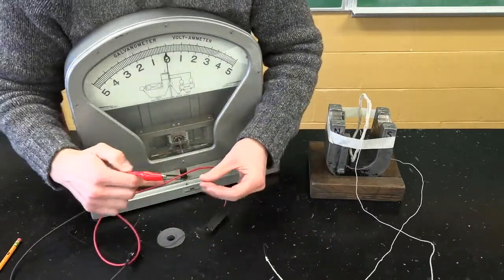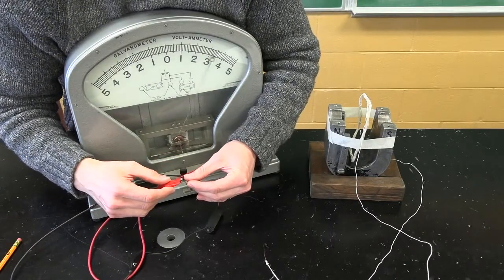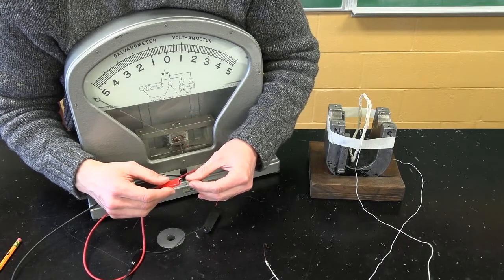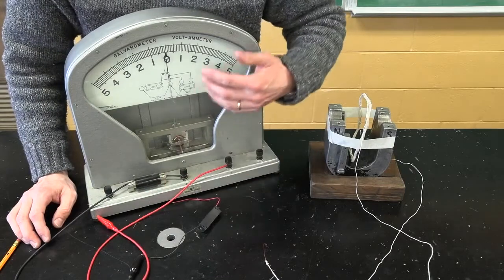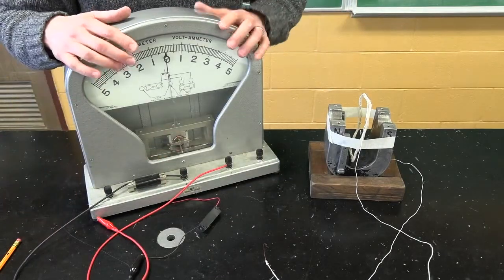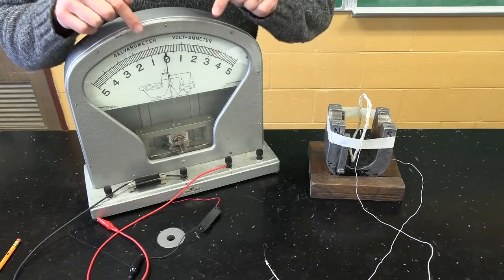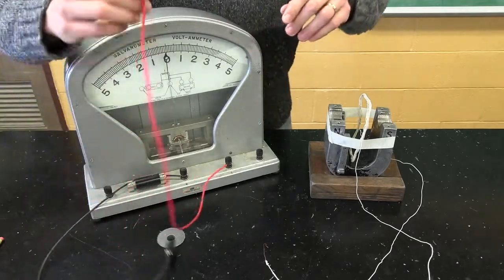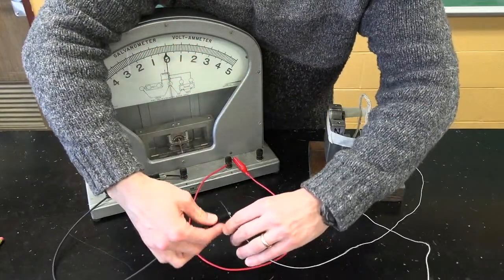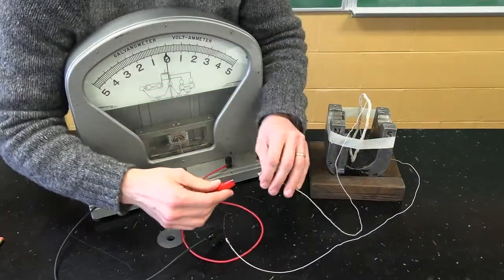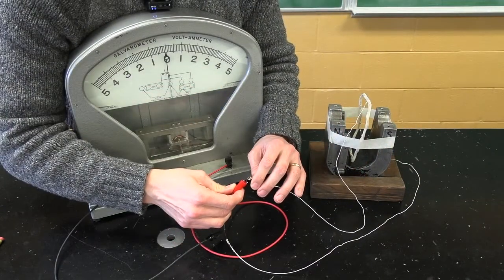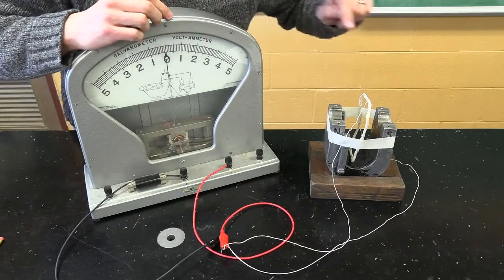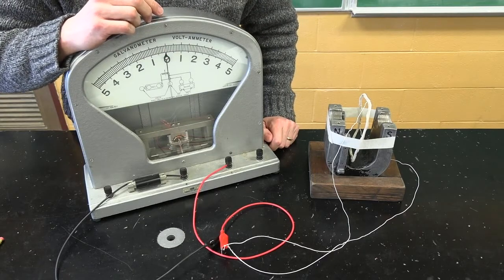And watch the galvanometer when I just touch this to the positive here. You see the needle flies off the scale, right? So this 1.5 volts blows the galvanometer away because this measures very tiny, sensitive voltages. So if there is any voltage, this will be able to detect it. Let me connect first this wire here and now the other wire. So we've got a lot of flux. Let's see, do we get voltage? Nothing. No movement, no voltage in that coil, even though we've got a tremendous amount of flux.